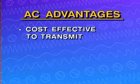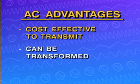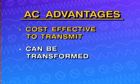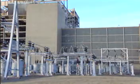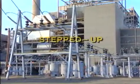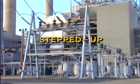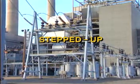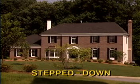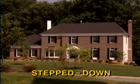A second advantage is that AC can be transformed to different voltage and current levels, allowing it to meet the needs of many different components in circuitry. Because of its changing direction, an AC voltage can be more easily increased or stepped up for transmission, as happens to the voltage being distributed from a power plant. Likewise, it can be decreased or stepped down before it reaches its destination, such as your home.